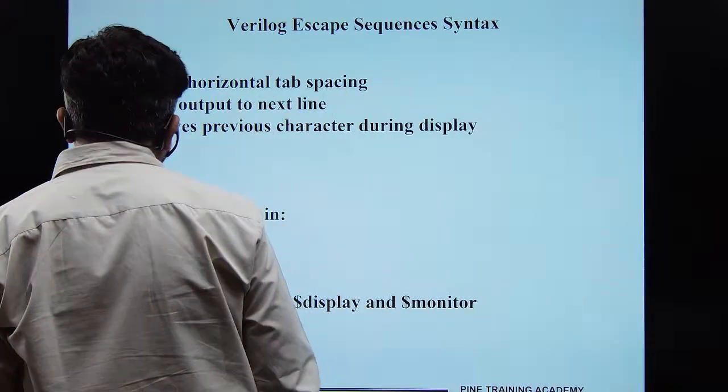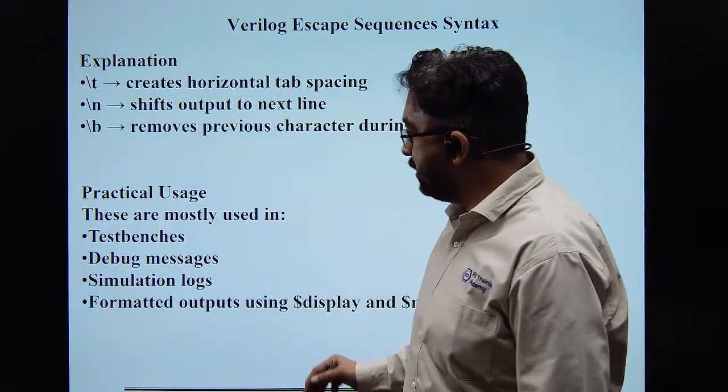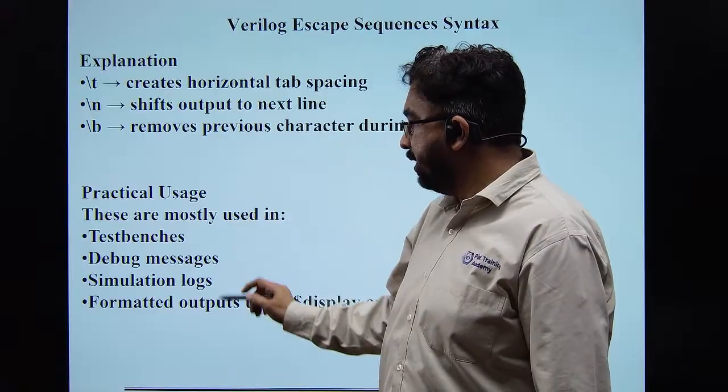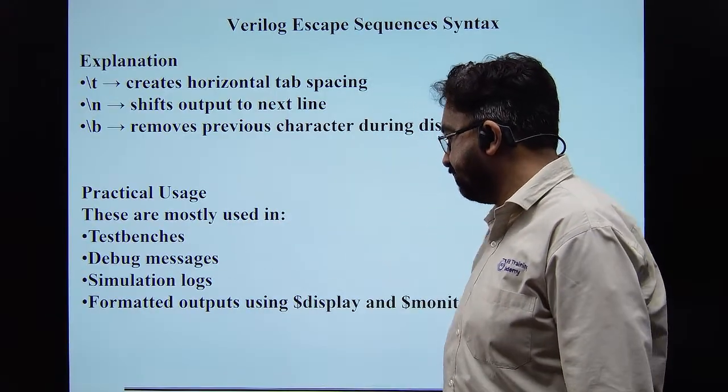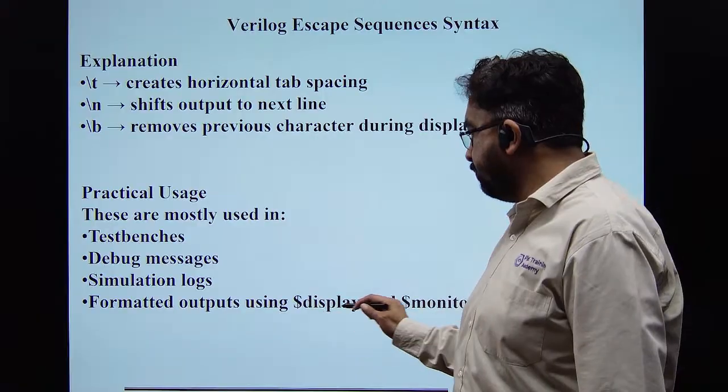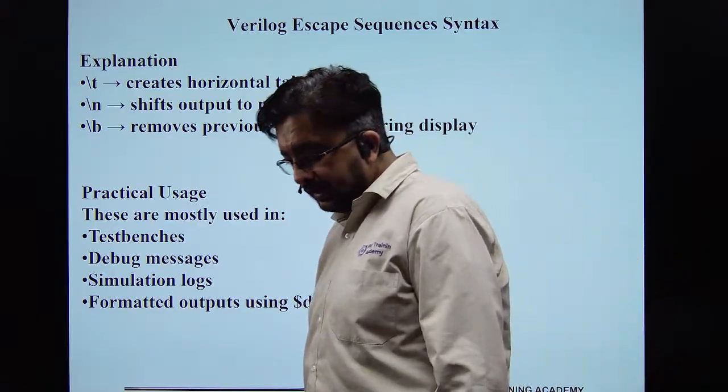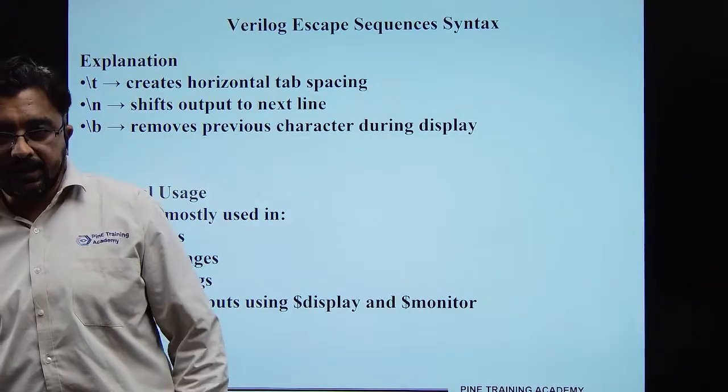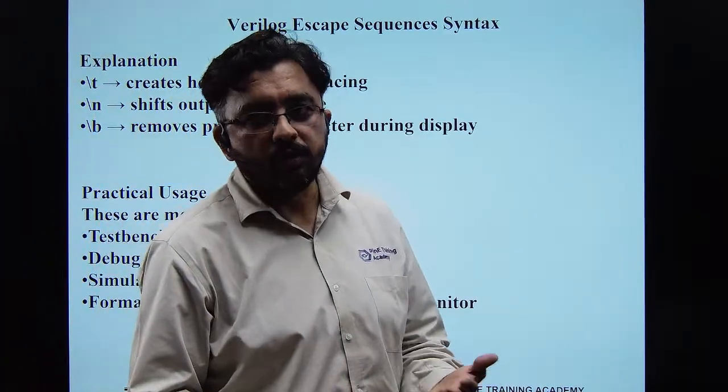So what is the practical use? They are mostly used in test benches, debug messages, simulation logs, and formatted output using $display and $monitor. $display and $monitor are generally used to see the outputs.